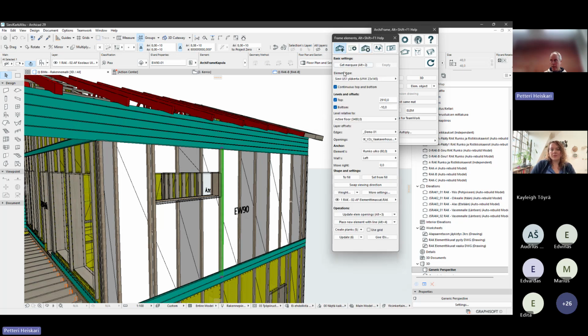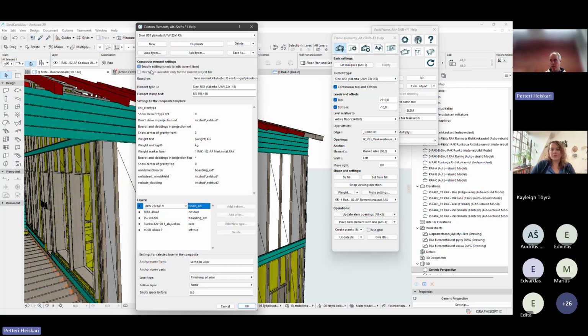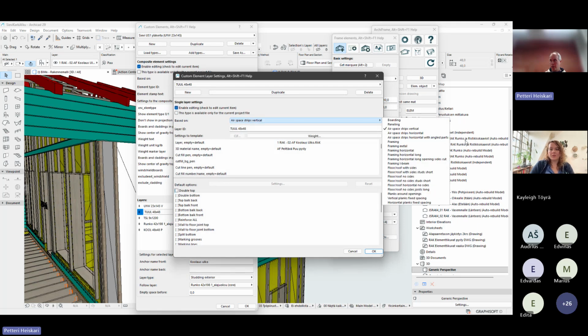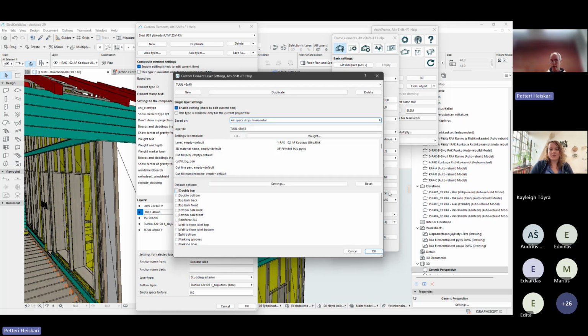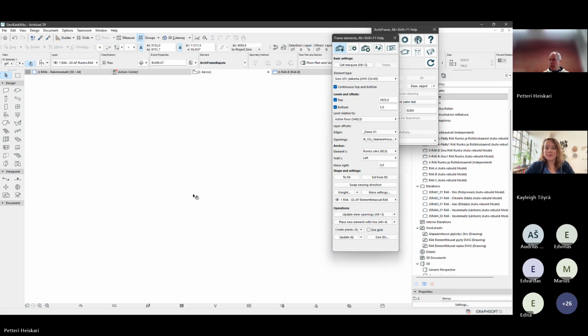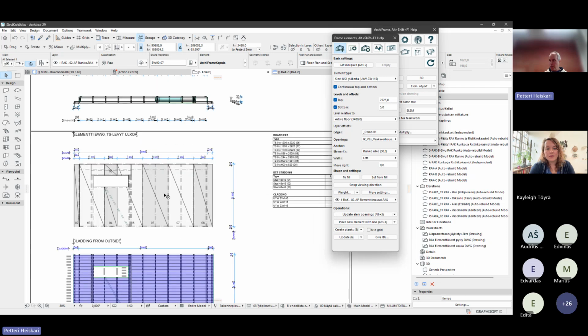And let's jump to the element settings slightly at this point to show how you would define it as horizontal. So now this is the raised base layer with material 48 by 48, and it's defined as airspace strips vertical. So this would produce then horizontal ones. Since we have horizontal cladding, I will not change the definition of this element, but that was the place to define it. And then let's continue with our work to produce CNC for framing station.